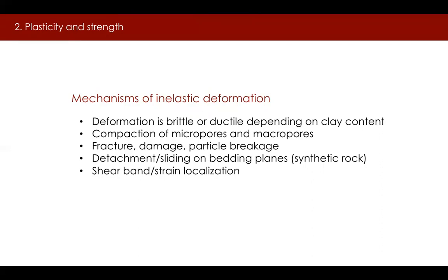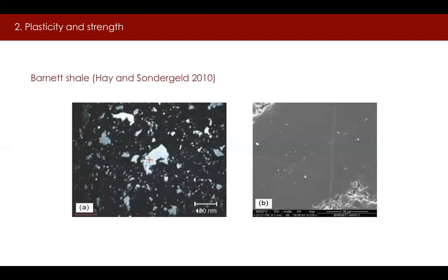Inelastic deformation could be due to compaction of the micropores and macropores, fracture and/or damage including particle breakage, detachment and sliding on bedding planes, and shear band or strain localization. The degree of inelastic deformation in a rock depends on the load level.